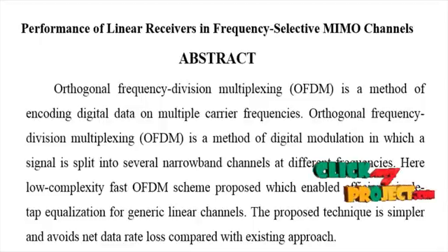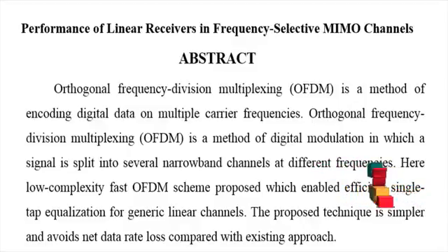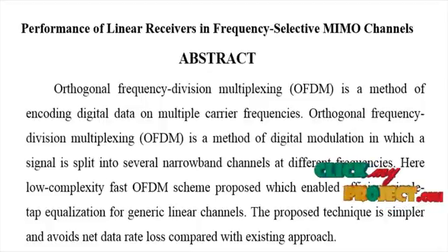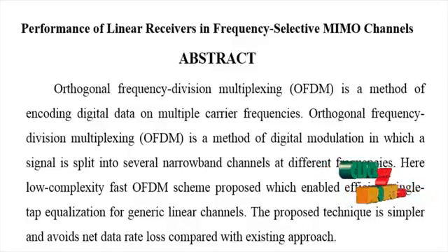The complexity and performance of the SCFDE system is comparable to that of OFDM, while avoiding the above-mentioned drawbacks associated with multi-carrier implementation. On the other hand, FDE does not represent an optimal solution to signal detection over ISI channels, and SC systems cannot offer the same flexibility as OFDM in the management of bandwidth and energy resources, both in single-user and in multi-user communication.